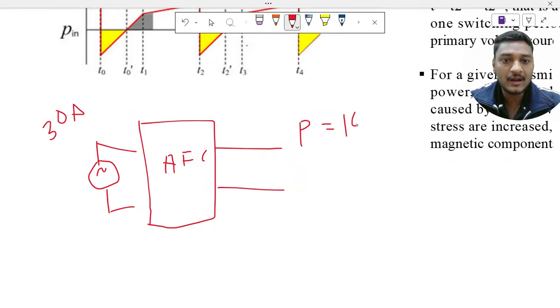Okay, so with a 10 kilowatt power requirement, here is one resistive load with an AC to DC converter. My power requirement is 10 kilowatt, so it is drawing 30 ampere of current. Now what happens when I replace this load with my DAB converter?